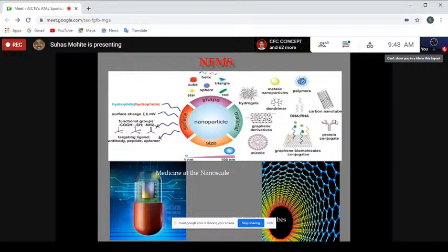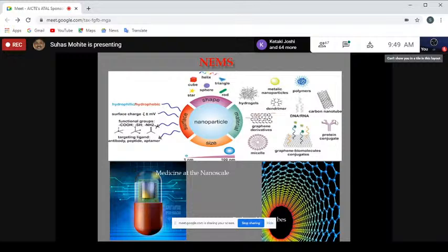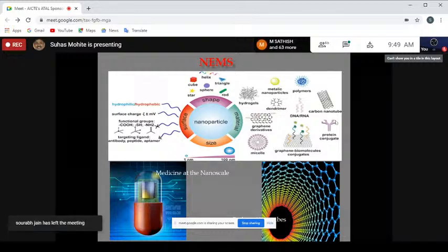And with these scales, you have several other significances attached to the changing scales of milli, micro, and nanoscale materials, because you have the response times scaling in the same order, that of milliseconds, microseconds, and nanoseconds, or the operating frequencies that we can use are in kilohertz, then megahertz, and gigahertz. So that is how things are also scaling alongside. When the physical dimensions undergo change, the time scales also undergo change. That is something you have to keep in mind, because the device response time also shrinks considerably by orders of magnitude. We used to have kilobyte memories, and megabyte, gigabyte, and now terabyte memories are possible because of the shrinking length scales of these devices.